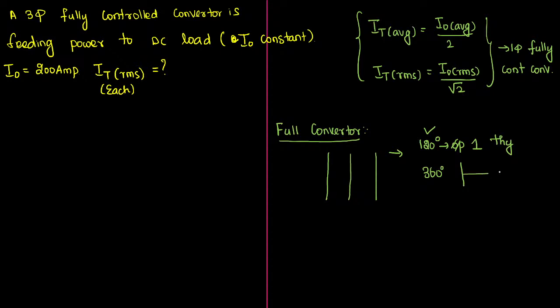In order to complete one complete sinusoidal waveform, we will be taking 360. In the output, our focus should be up to 360, whereas through the thyristor we are receiving only current up to 120 degree. In the output, they have taken the output current. They told that output current is ripple free, constant current.